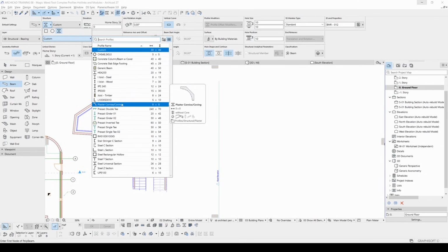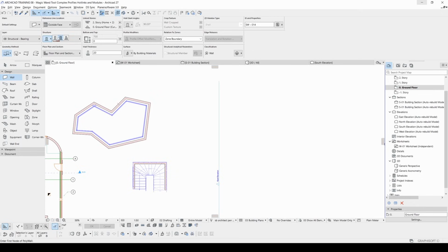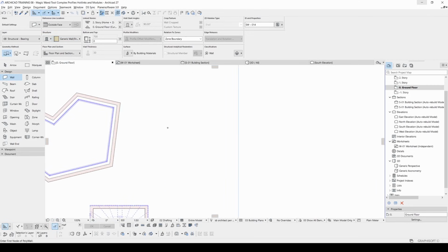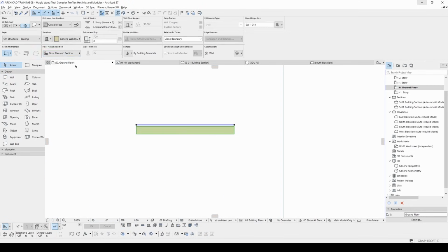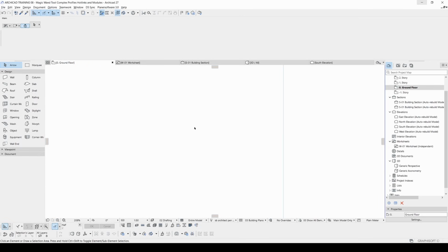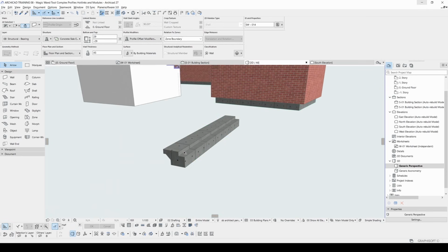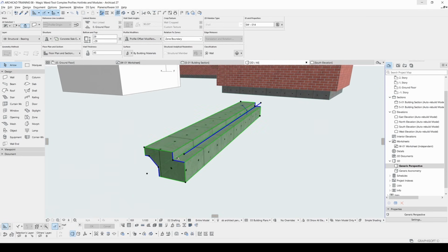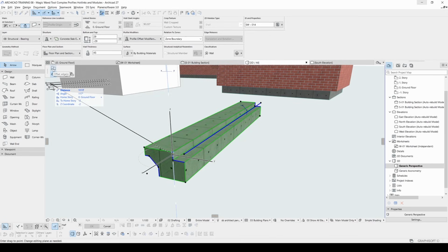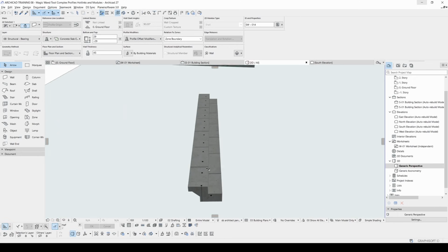that we sketch. Not only this, if you go to the wall tool, if you go to structure, in the previous lesson we learned how to create composite walls like this, but we can also use complex profiles for the structure of the walls. For instance, concrete slab edge footing. And this is a kind of complex profile. You can edit them by clicking the edge, offsetting them. It's also a very clever and smart tool.